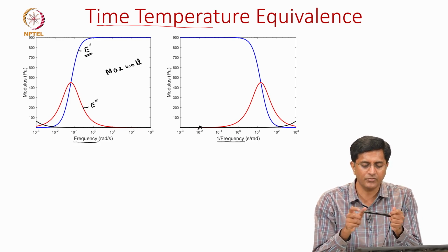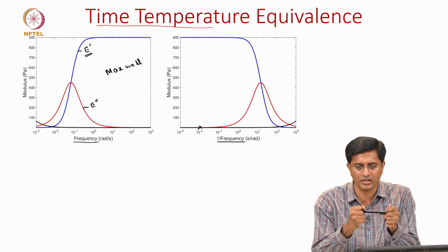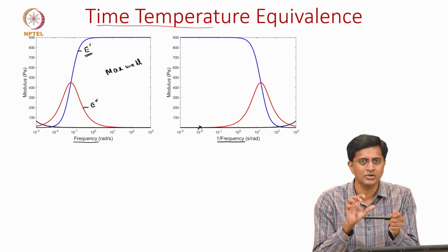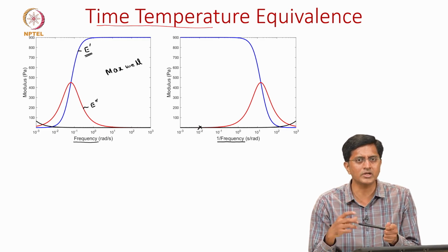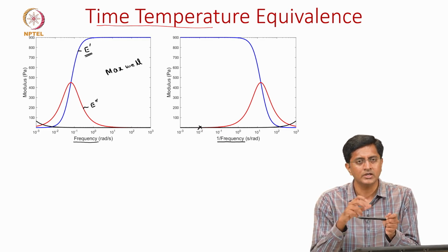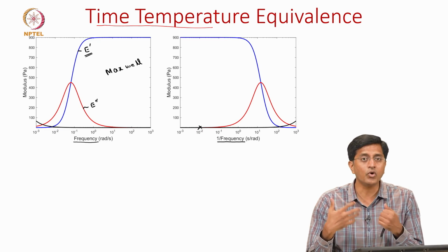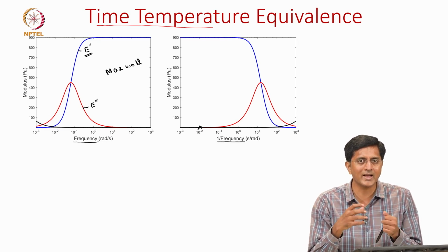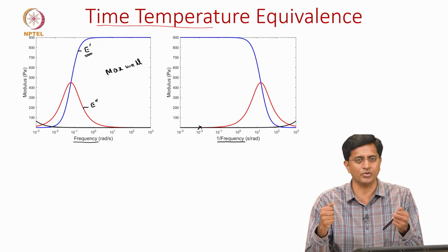It is almost like doing a tension test, either stretching or compressing very quickly. So, there is less time to deform. From our molecular structure discussions, we know that if we are loading quickly, the chains have more resistance to deformation, because you are not giving them enough time to relax and accommodate the deformation.